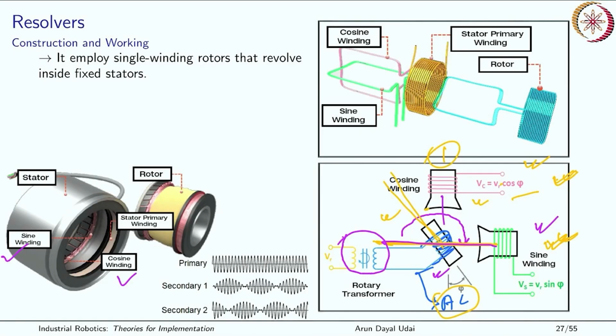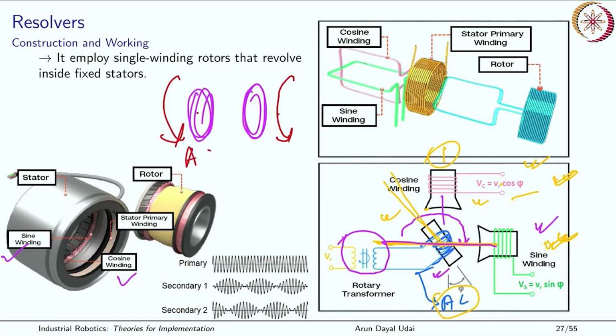Okay, so you have a coil like this, and another coil like this, both rotating about their own axis, and this axis is also rotating. If this coil carries AC, the other will also carry an AC signal of the same frequency. The amplitude may be different, that depends on the flux linkage between them. So this is how you can transmit AC from one coil to the AC on the rotor.